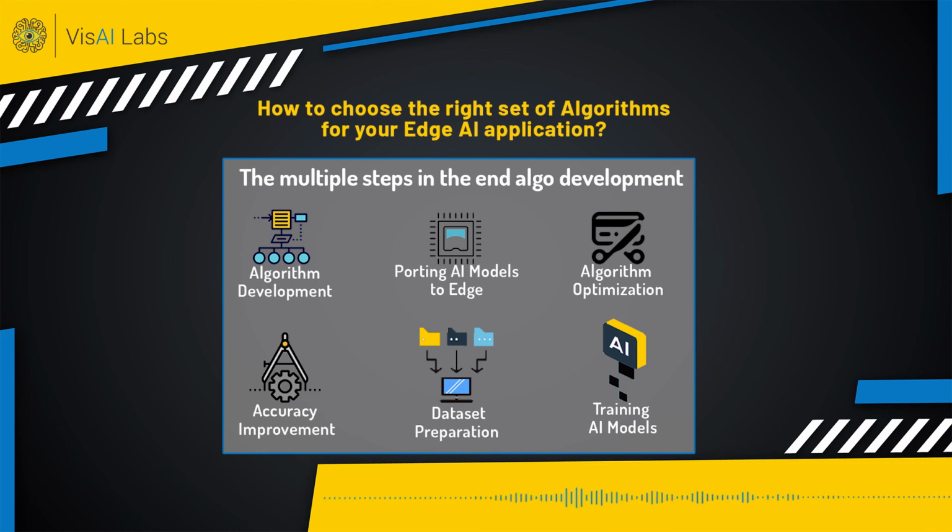The reason is these models are generally heavier to run on a small device such as an Nvidia Nano, a TX2, or a Xavier from Nvidia. So we employ techniques such as pruning, where we figure out that if there are, say, 50 layers, some of the layers are not contributing enough to make a decision.